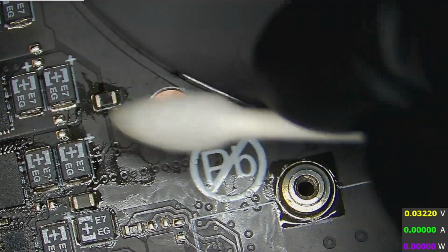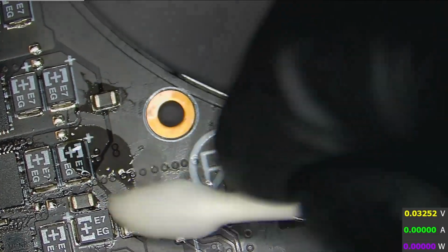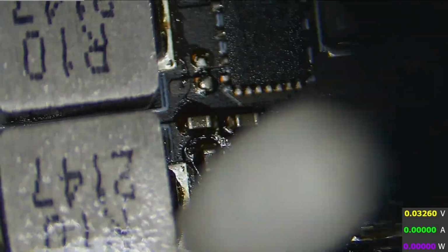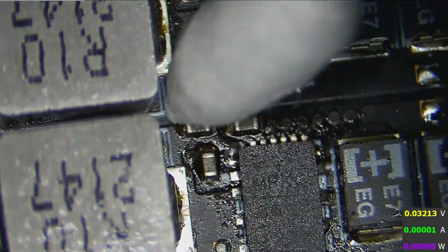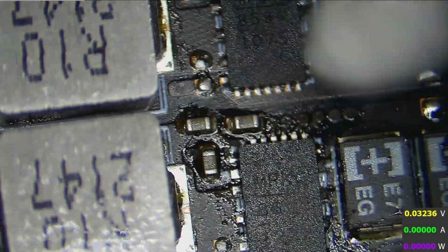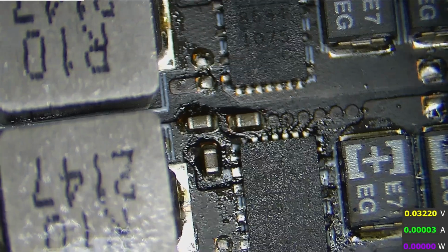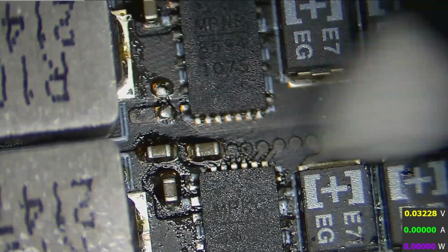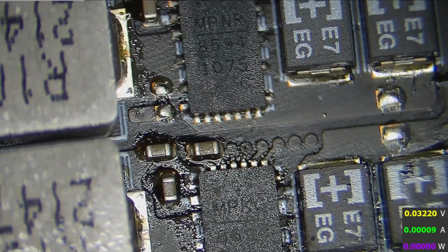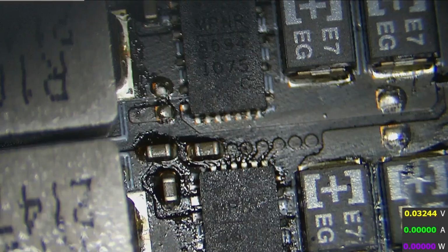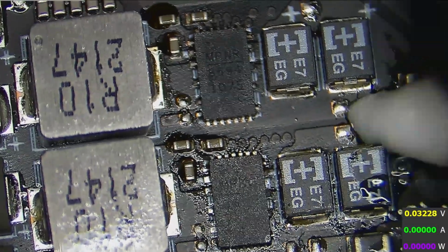I think it's when we had a video on it. It was just a short on main with a bad capacitor. But that one did actually have a full schematic with a power sequence diagram for that machine. And we can see the third rail to come on is just the power button. There's generally some setting in the BIOS like wake on charger or something like that. But most of the time these things won't actually go through all power stages just off the charger. You need to press the power button on the computer basically.